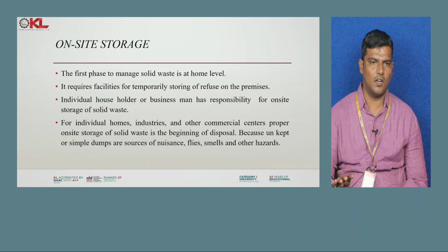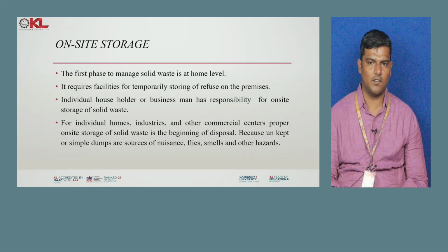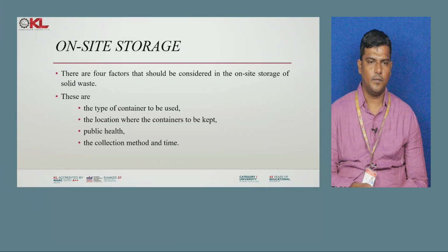As I said, on-site storage is the first phase of managing solid waste at home level, and it requires facilities for temporary storing of refuse on the premises. Individual householders or businessmen have the responsibility for on-site storage of solid waste. For individual homes, industries and other commercial centers, proper on-site storage is the beginning of disposal, because unkept open dumps are a source of nuisance, flies, smells and other hazards. There are 4 factors to be considered: the type of container to be used, the location where the containers are to be kept, public health, and the collection method and time. Generally we prefer to collect the material day by day so that nuisance will not be created.